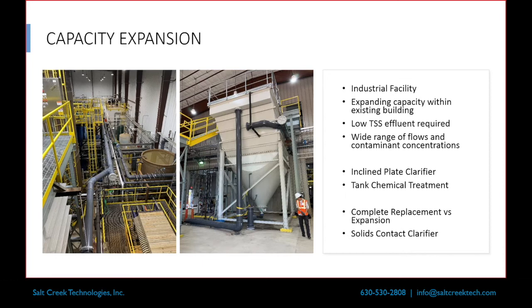And then we went with the tank treatment system because pipe flocculation, the reactions that we were doing took some time. So we wanted to have enough residence time in there to actually get everything done to completion. And two, the flow variations were high enough that you couldn't really effectively design anything else.